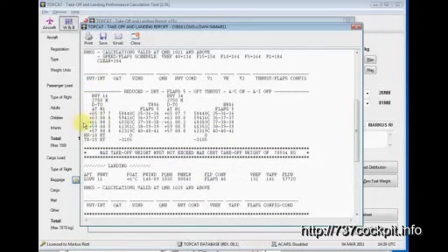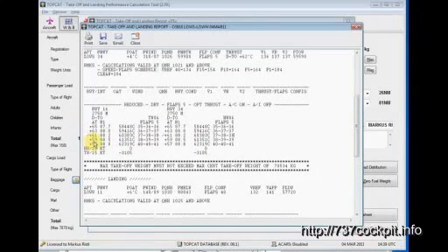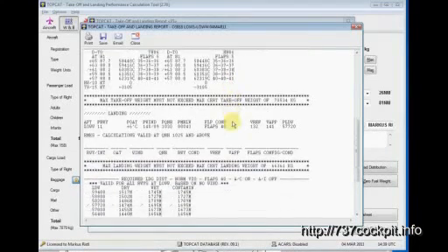Our takeoff calculation is marked with a slash before. Slash means that this is the calculated outside air temperature, so that our engines will give a thrust of 88.2%, which leads us to 137, 138, and again 138 V speeds in flaps 5 configuration set.